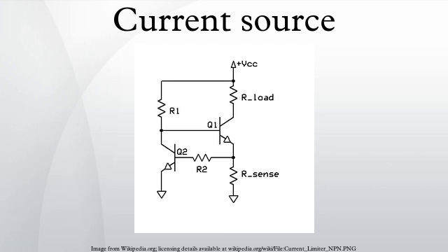LED current source. The Zener diode can be replaced by any other diode, for example a light-emitting diode LED1 as shown in Figure 5. The LED voltage drop is now used to derive the constant voltage and also has the additional advantage of tracking VBE changes due to temperature. R2 and R1 are calculated as given, where ID is the LED current.